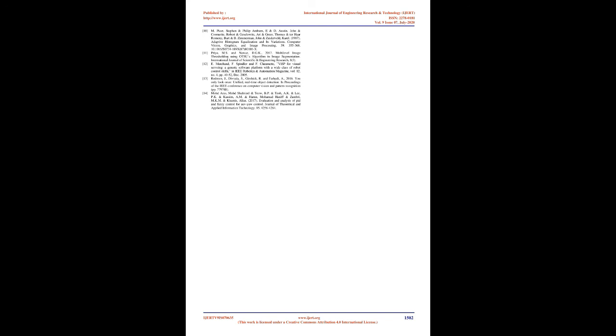A ROS-based software structure is developed to perform multiple tasks simultaneously. Every feature such as object detection for an open gate, path-following capabilities, and the controllers for stability has been realized through its separate node. Nodes are classified into subsystems to reduce the complexity and for ease of communication among them. While a lot of improvisations have been made in this model as compared to previous ones, there is still a possibility of integrating more advanced systems like acoustics and sonar for better navigation of the vehicle in more adverse conditions.